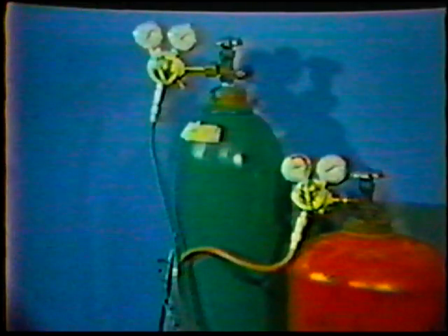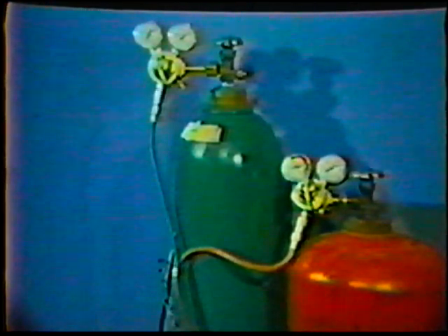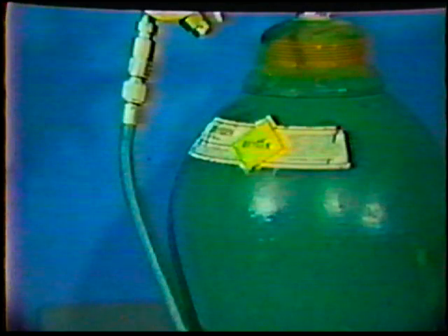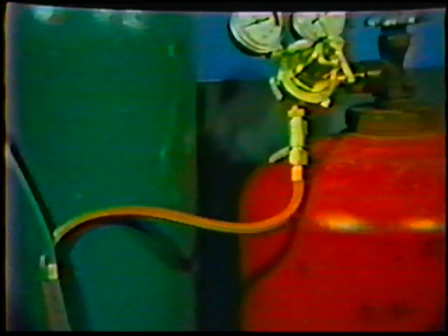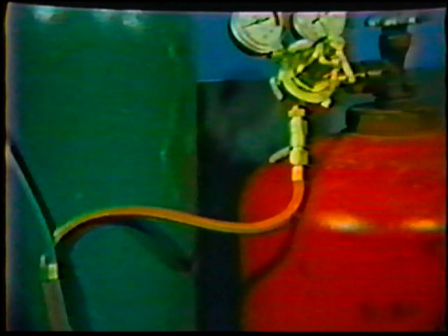The hoses used with this process are specially designed to be used with oxy fuel systems and are color-coded to ensure proper use. The oxygen hose is green with right-handed thread fittings. The acetylene hose is red with left-hand fittings. For most applications, the hoses are 3/16 to 3/8 inch in size and 25 feet long. When the gas supply is within 25 feet of the work site, the 3/16 inch hose is adequate.